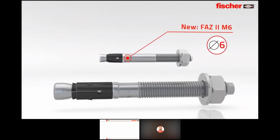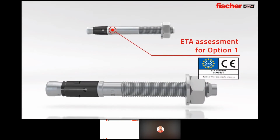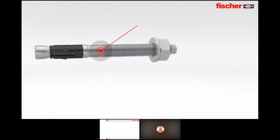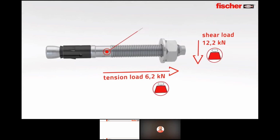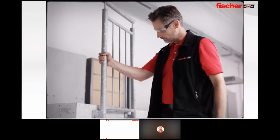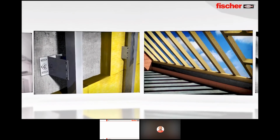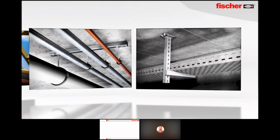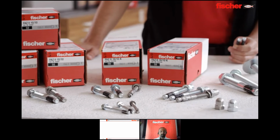Brand new, the FAZ2 M6, the first bolt anchor worldwide with drill hole diameter 6 mm and ETA option 1. Maximum load with maximum embedment depth for the FAZ2 with diameter 10. The perfect solution for fixings of railings, facade substructures, tension anchors in timber construction, pipe routes, cable trays and much more. The Fischer FAZ2. This is how versatile power can be.